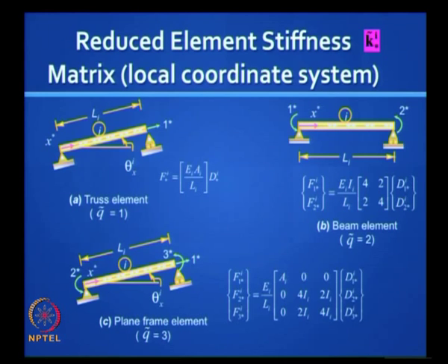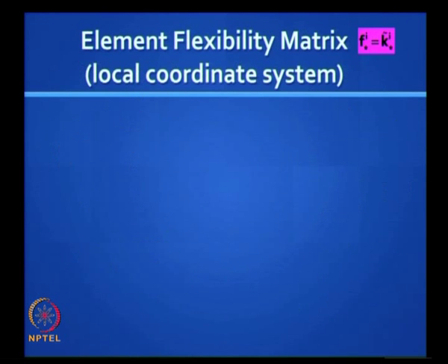That's what we do in first order analysis. We will study later in the 7th module, there is an interaction because it behaves like a beam column. Right now we pretend there is no interaction. Not only we, all the software packages also happily pretend that there is no interaction, but actually you have something called a P delta effect, which we will see later. That is called second order analysis. Does it make sense? Okay.